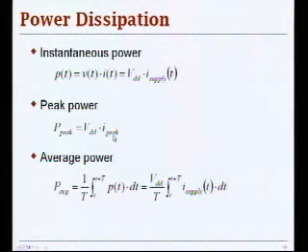The peak power consumption is basically, over some period of time, you take the maximum of this current over that same period of time and you define this peak power. The reason why peak power is important is that you have to design your power distribution network for the worst case to be able to support all these transients when you have more current than average for your circuit to work.